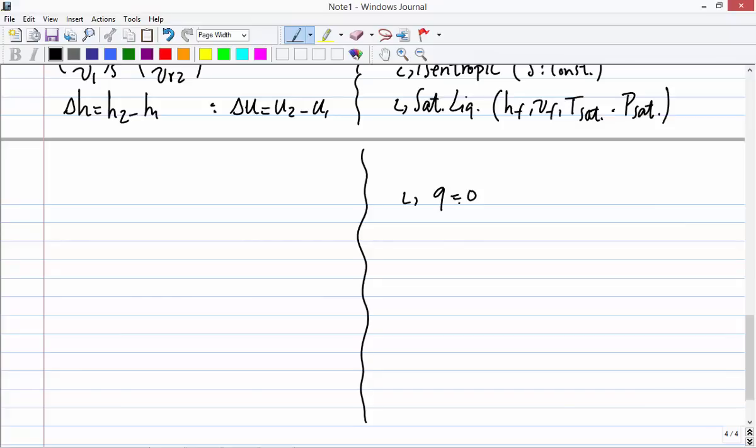It's just work. And how do we solve for work? W pump in. Let me write it this way. W pump isentropic. Because I'm assuming that process 1 to 2 is just a straight vertical line from point 1 to point 2 right above it, and entropy does not change.